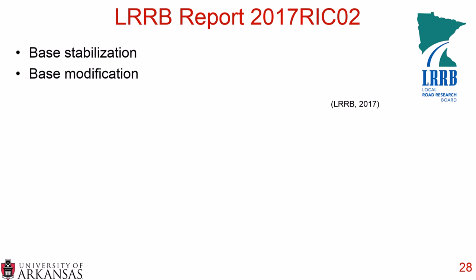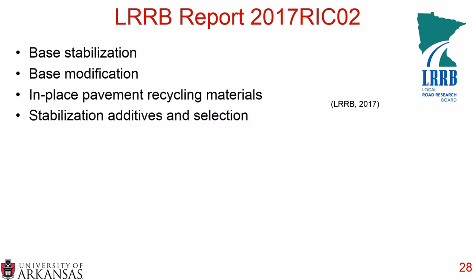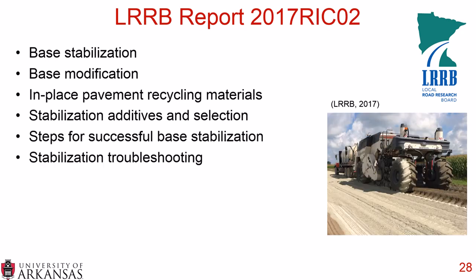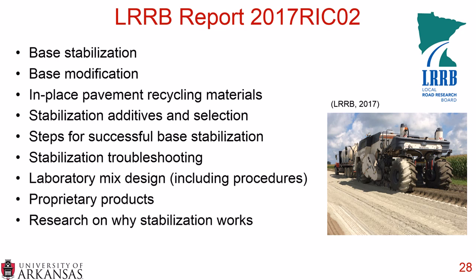So LRRB Report 2017 RIC02. This covers base stabilization and base modification. It looks at in-place pavement recycling materials, and it talks about stabilization, additives, and selections. It also includes steps for successful base stabilization and any sort of stabilization troubleshooting. It includes a laboratory mix design and the associated procedures. It talks a little bit about proprietary products, and it also covers some research on why stabilization works.